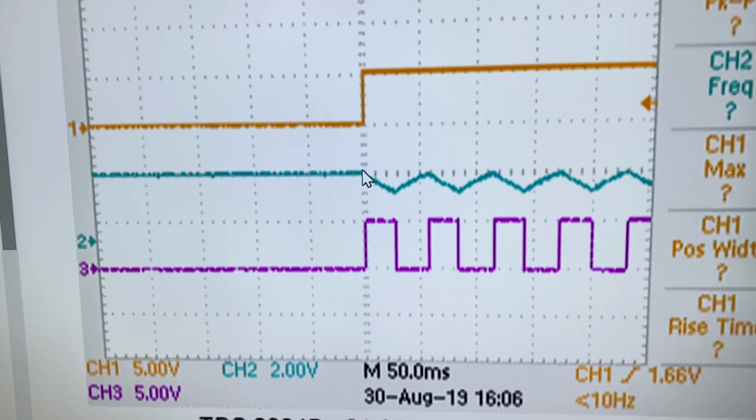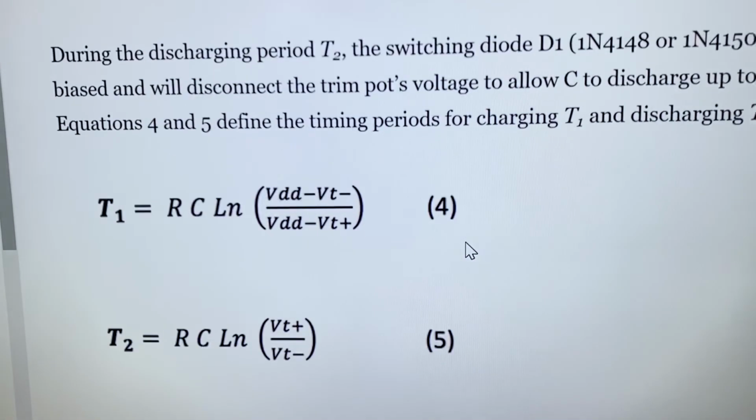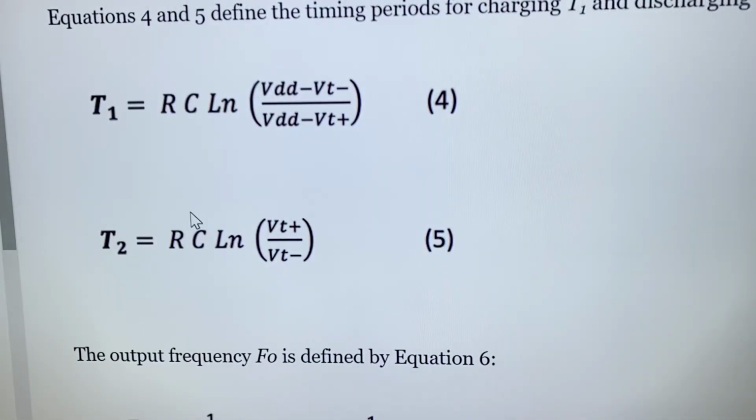And then you can see how the discharge starts here. And now you didn't have to start from here, from VDD, from high volts. So you start from VT positive to VT negative, VT positive and VT negative. And now you can get the frequency immediately and accurate, and that way you will be able to use it in your instrumentation designs.